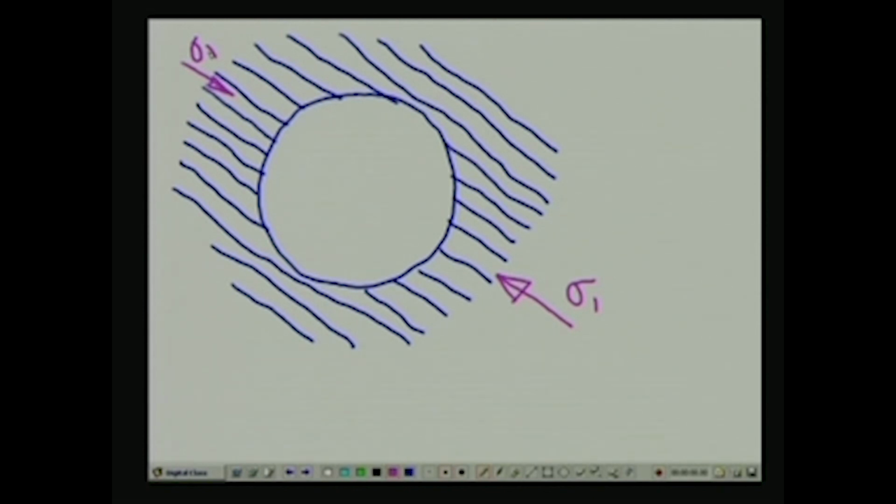So in this case, what is going to happen, the laminations to the top and left of this particular tunnel, particularly in this area, are likely to squeeze into the tunnel because of the release of stress during tunnel excavation. And so perhaps after a while you are going to end up with a tunnel bore of this type.